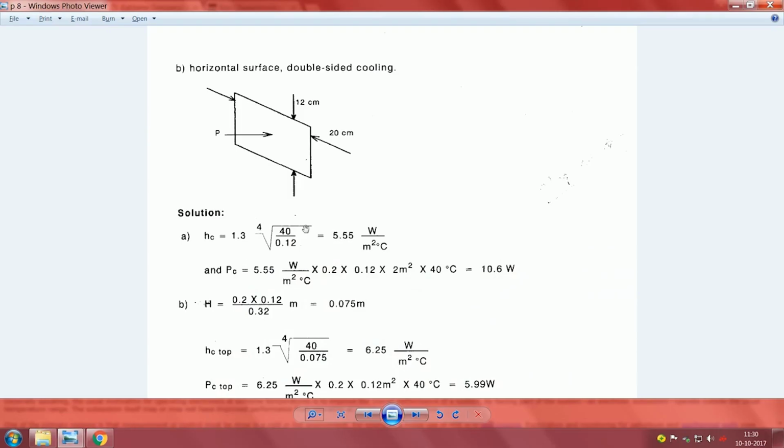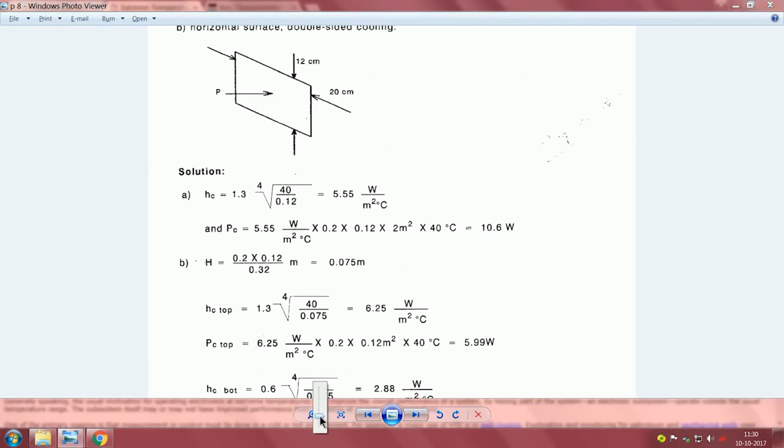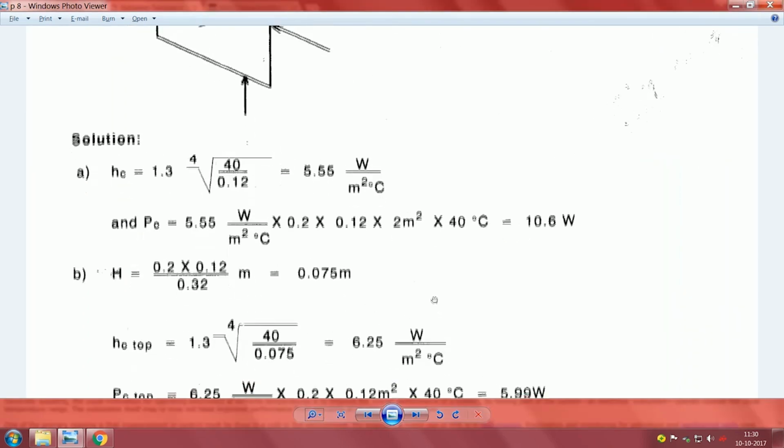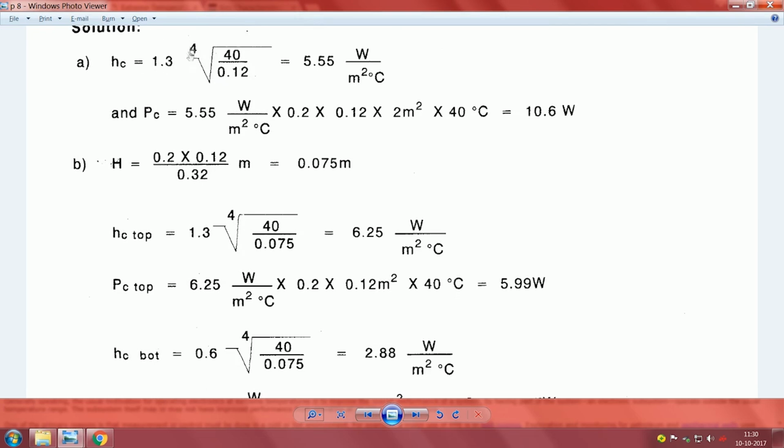Imagine the ambient is 55, the plate can still be at 95 degrees centigrade, which is not an impossible condition. So, things have been calculated, saying in the vertical condition we have 10 watts. And in the case you kept it in the horizontal condition, you have seen this is 0.3.